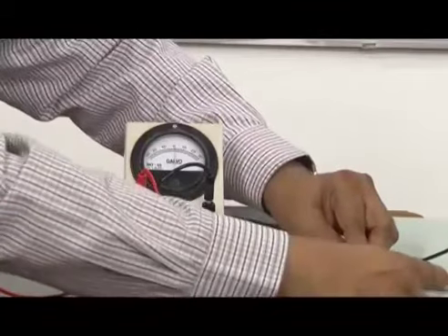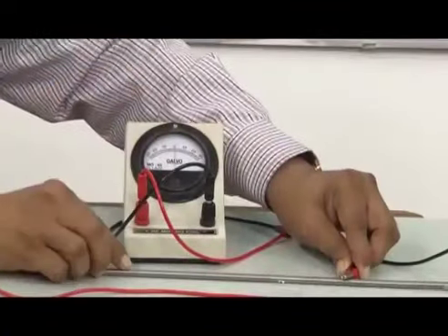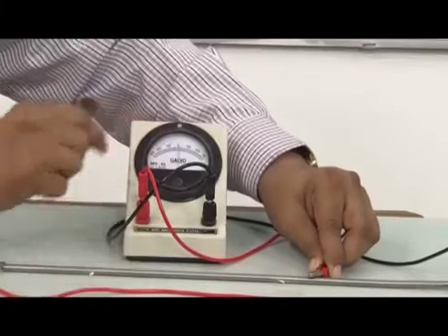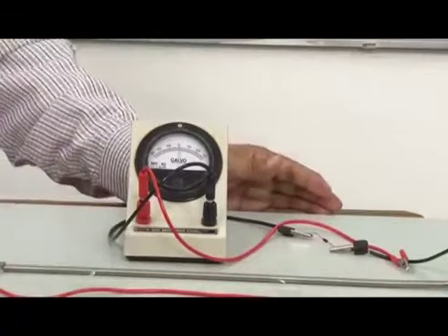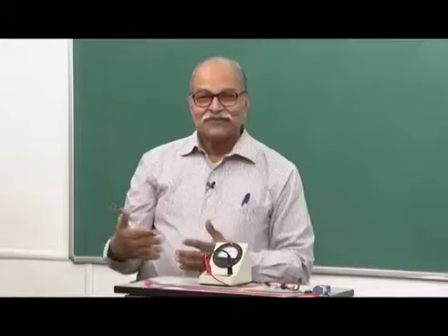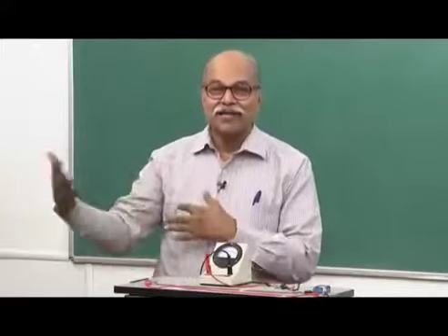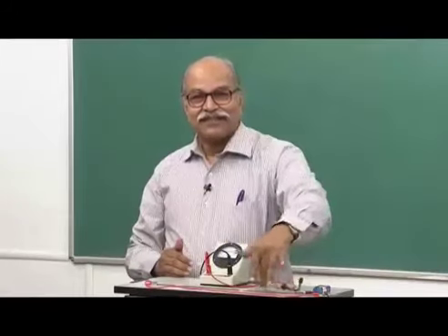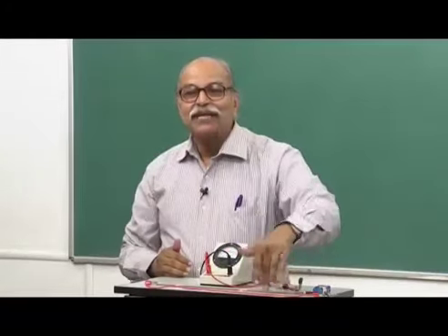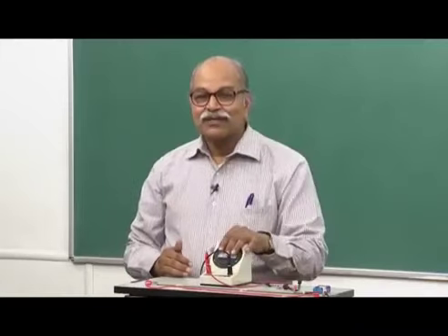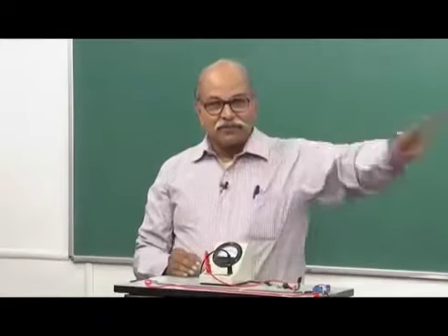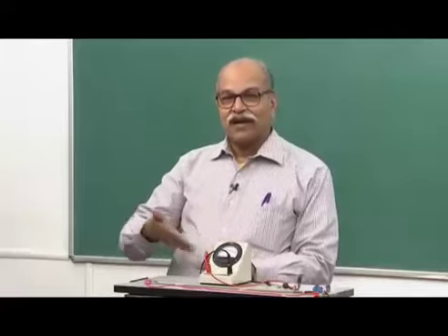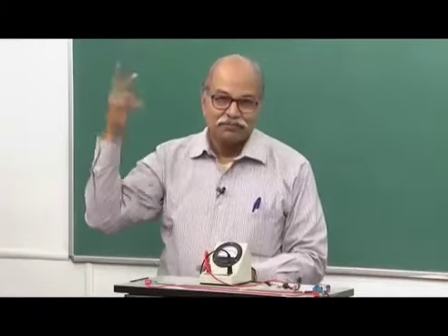In the reverse bias, even if you apply large voltages, though you should not apply voltage more than the breakdown, you have seen that I have applied reasonably large voltage here and there was almost no current, at least not visible in this instrument. So, reverse bias almost 0, and forward bias, after that knee voltage it goes up.